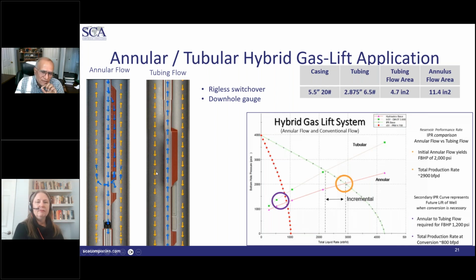In order to make the gas lift work, you have to remove multi-pointing and you have to inject at the right location. Now, with the changes, looking at this IPR versus this IPR, your injection point has to be significantly different, right? With the lower pressure, your injection point moves deeper. At that time, if you have to pull the valves, some people may not use side pocket mandrels; they are using conventional mandrels. In that case, they will have to pull the entire tubing.